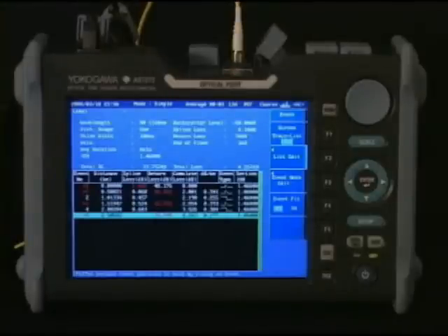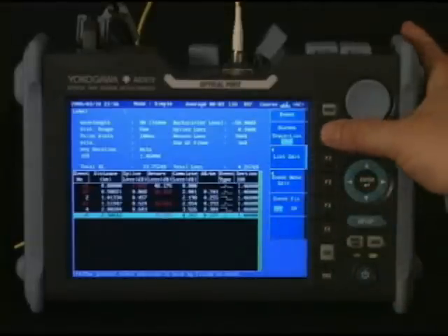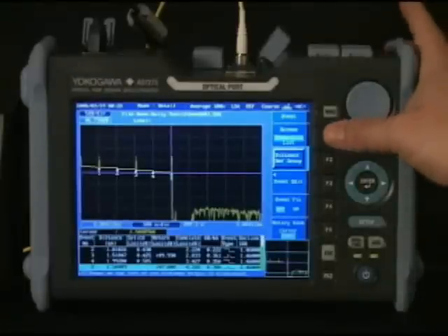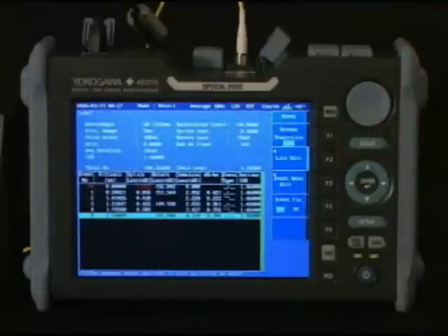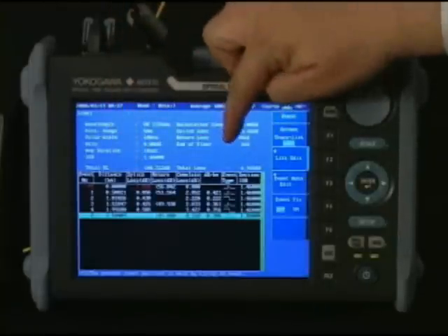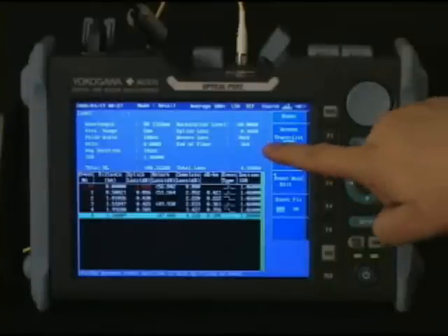Events are labeled on the trace and their measurement data is provided. Analysis is critical for most OTDR users. Here on the trace list screen, you can see all the conditions for measurement are provided at the top. This includes what is defined as an end event, what the loss threshold is for a splice, the IOR, and even the duration of the test.